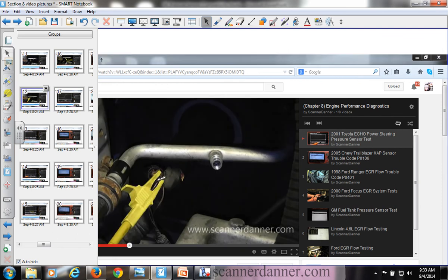Okay, doing some further wiring checks. My signal was 0. I need to check the rest. Agreed. In particular, my 5-volt reference. Do we care about the ground if the sensor signal voltage is 0? Probably not. Definitely not. I'm not worried about the ground. I think I show it anyway, but I'm not worried about it.